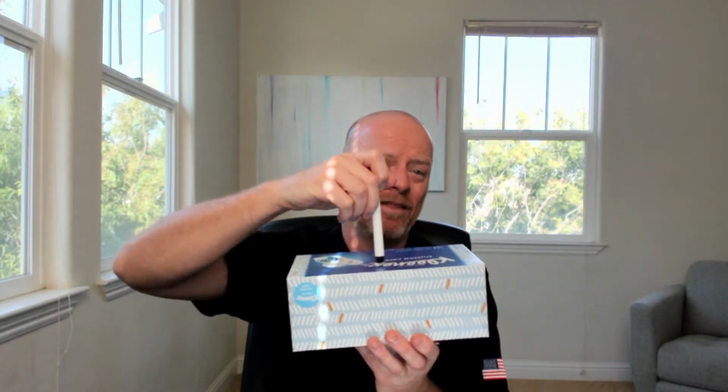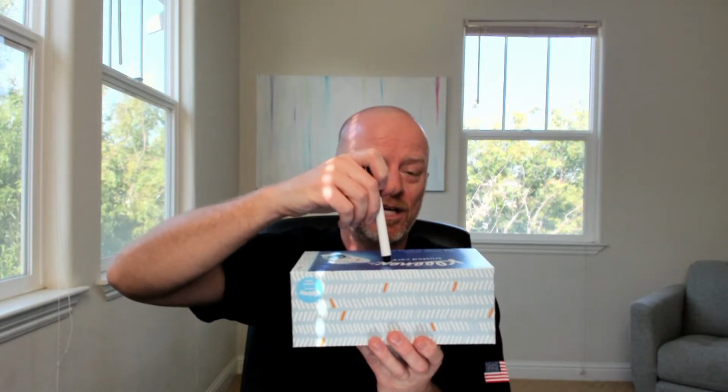Yes, so if I have that part sitting in my machine, I've got my box here. Right. So if you drop the part in your machine, if you have a probe, it will automatically come down, hit all the sides, and establish where that part is living on your machine. If you don't have a probe, you'll have to manually find that, and we usually use an edge finder. So hopefully that brings some clarification on what we're doing here with the probe.